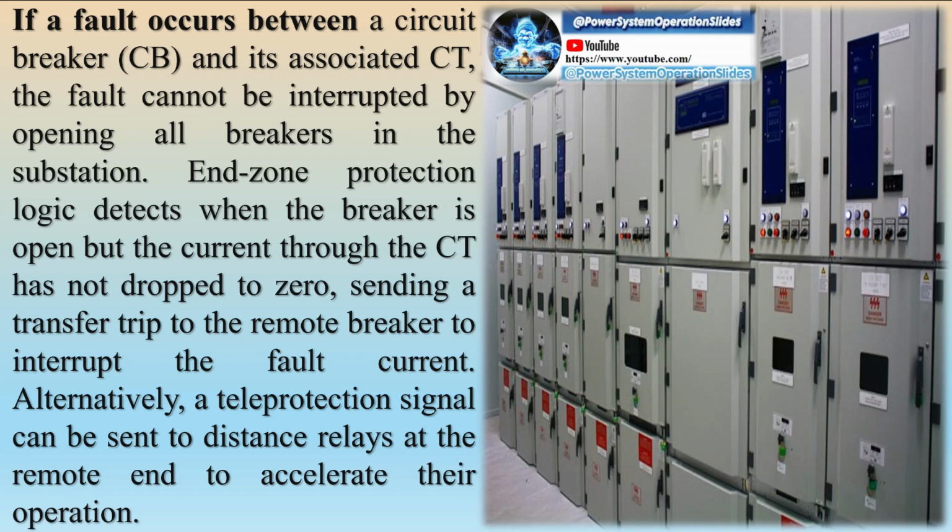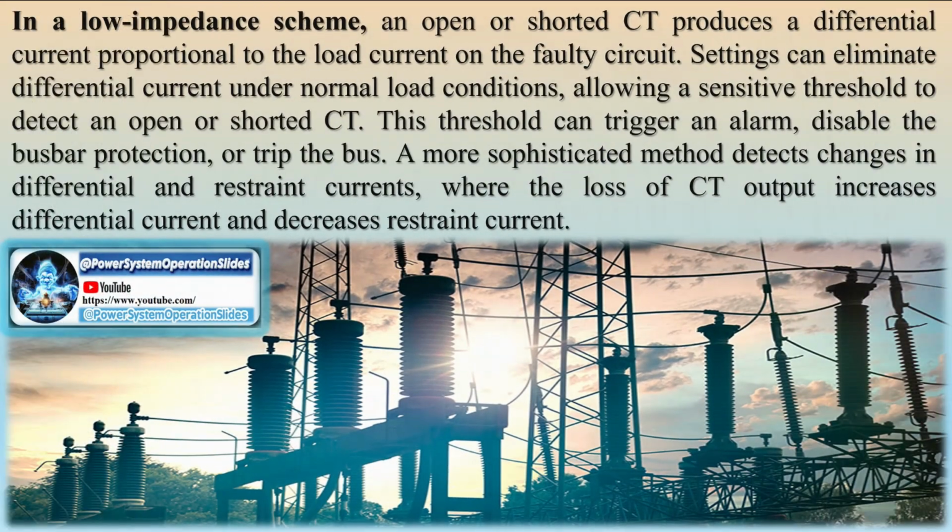Purpose: busbar protection systems safeguard substation busbars and associated equipment from short circuits and earth faults. Historical context: initially, no separate protection devices were used for busbar protection. Remote end-line protection served as the main protection for busbar faults. Evolution: increased network short-circuit capacity led to the use of dedicated differential relays for busbar protection.